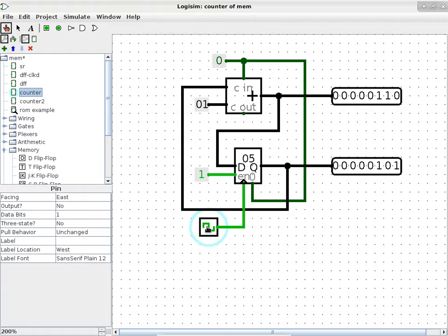The actual width of a shift register can be any width, but it only takes up 2 lines to control its content. And the reason why you can do that is because it's kind of like a class like this. If I want to pass something, I just give you something, and then you pass it on to the next person. If I give you another bit, you pass it on to the next person. So using this mechanism, I only need to give one person, repeatedly, different content, and by having a route of you guys passing the paper along in a class, I can have one single person, but I can specify the content of multiple bits within the class.